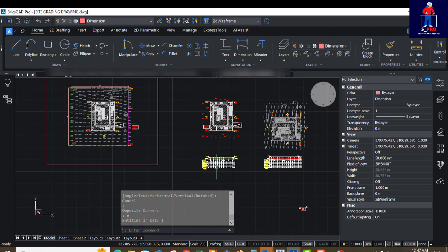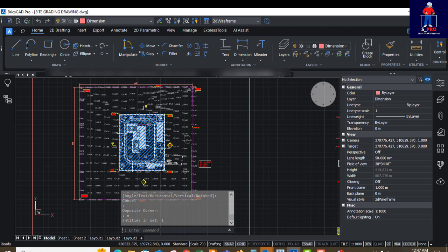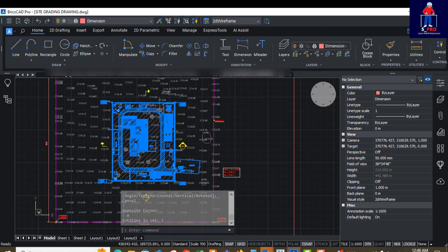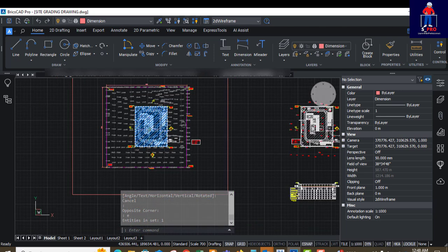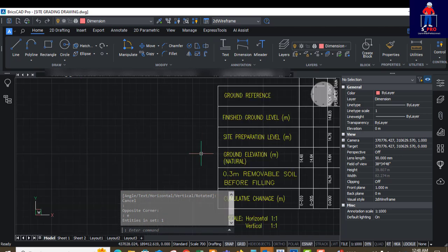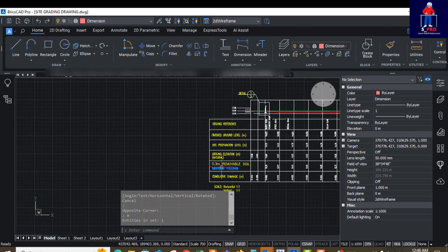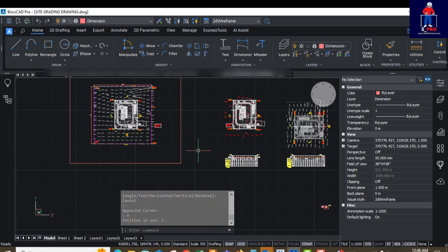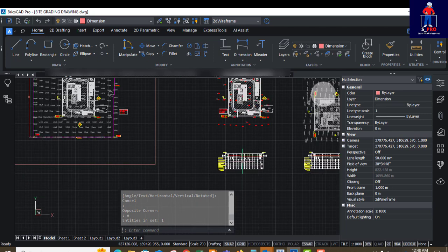It is advisable that before you start any construction, before you start bringing in sharp sand, you need to remove all the topsoil, the vegetation soil on the surface, to about 0.3 meter. That's 300 mm. Sometimes it's 150. So when you remove the topsoil, then you begin to bring in sharp sand, that will fill it.